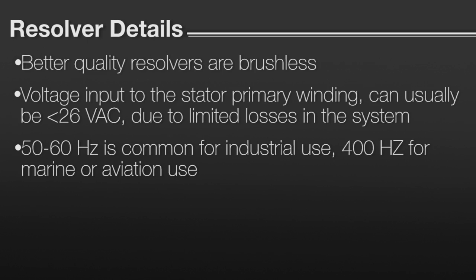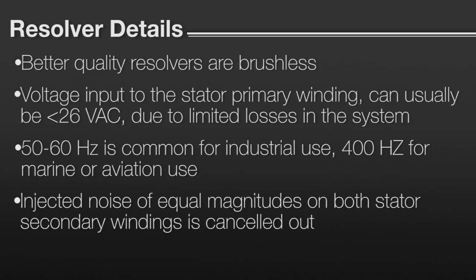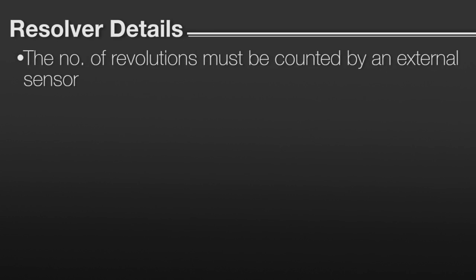And recall that resolver-to-digital converters run the signals on the stator secondary windings through an error amplifier. This has the advantage of canceling out noise injected on both windings. A little more about resolvers. The resolver-to-digital converter electronics is normally not purchased with the resolver, nor is it mounted directly to it. Here's the good news. Your electronics will be kept away from the harsh environment that the resolver experiences, particularly for temperature and RF interference. Now here's the bad news. You're normally going to have to deal with 2 different vendors if you're designing a system, and you need to make sure their equipment plays nice together.